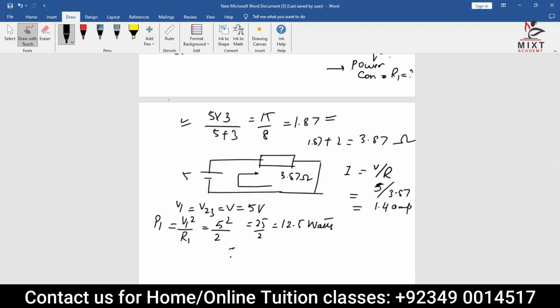So basically, your I23 will be equal to V23 divided by R23. So V23 was how much? 5, because it's a parallel combination, and divided by 1.87. So what is it? See, the voltage across V23 is 5 volts, which I just placed. What is the R23 value? R23 value is 1.87. So I need to find out the current through I23. It's 2.67.